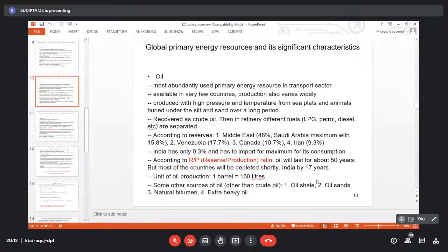So obviously, shutting down any of the boiler-based power plants is not very desirable from the energy consumption viewpoint. As far as possible, try not to shut down. Why is this required? Whenever the power demand increases or decreases and you want to adjust your power generation, the steam production also has to be adjusted accordingly. If it is reduced, steam production has to be less. Then what is your option? Say you have 3 units, like 3 into 200 megawatts. So obviously a total of 600 megawatts, distributed into independent units of 200 megawatts each.